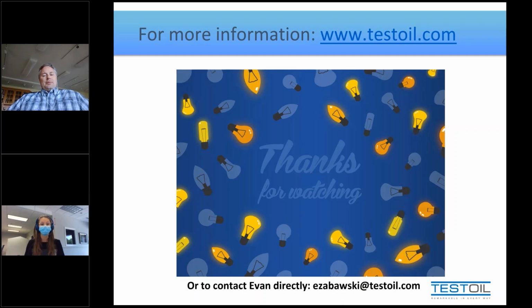So generally the answer is yes. With a shared lubrication system, if you can get it off the return line before the reservoir, on the header where all of them are dumping it back in, that's one of the best locations possible. If each machine feeds directly back into the reservoir independently, then you're probably best to sample directly out of the reservoir. Otherwise, it could be skewed by just one machine. So if you're going to do that, try and do it at the return side, not the suction side of the reservoir, if it exists, depending on the configuration.